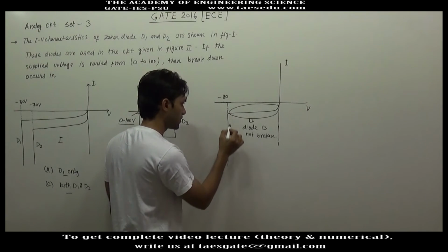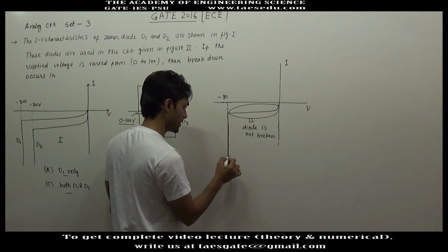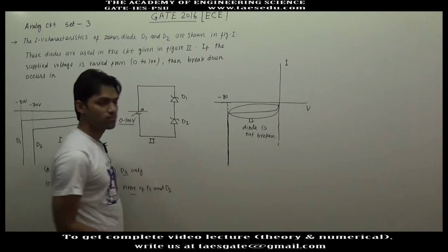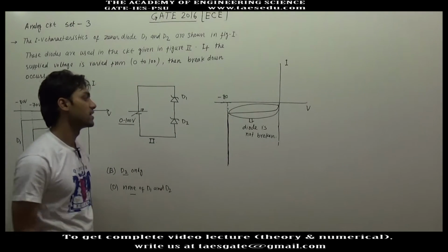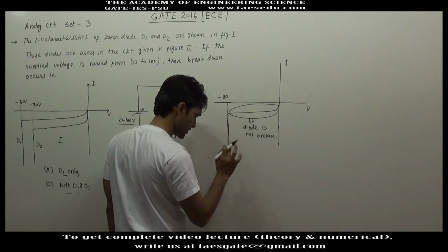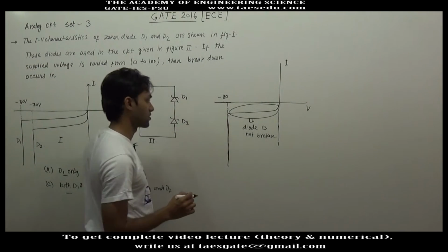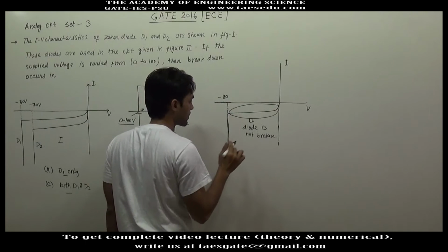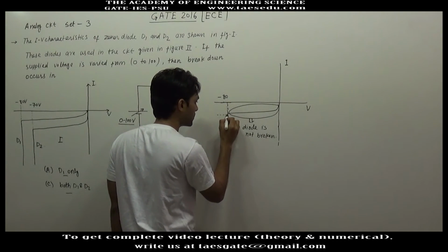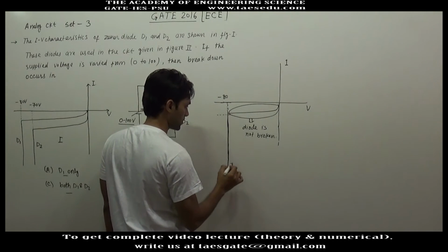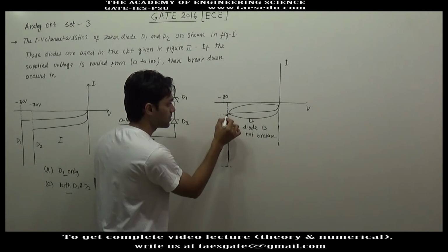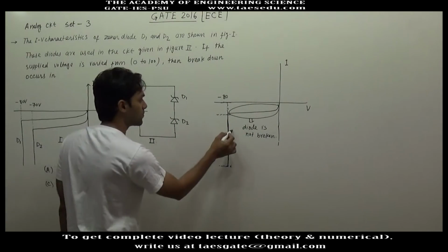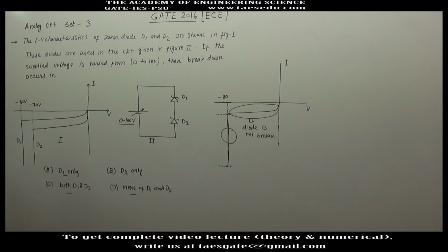the current, normally we take this line as, or we think that the meaning of this line is if the diode is broken, the current through it will be very high. But this is a misinterpretation of this line. This line says that if the diode is broken, the value of current may be anything between this value to this value. The current can take any value between the starting to the end values. The value of current will depend upon the external circuit. It is not decided by the Zener diode.